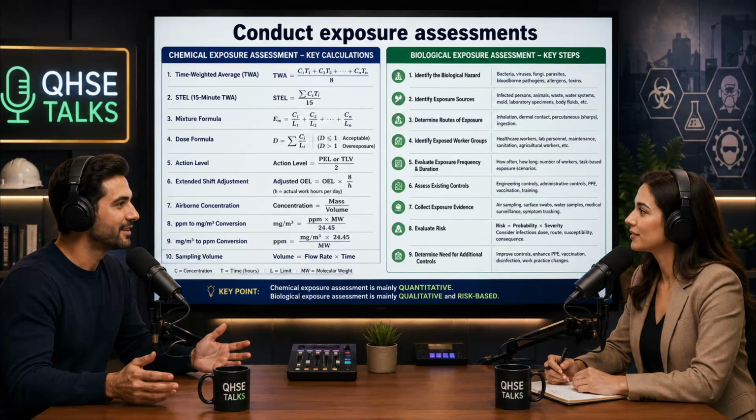Phew, now we evaluate the chronic full-day hazard. We run the TWA math. 15 minutes is 0.25 hours. So 25 ppm times 0.25 is 6.25. 10 ppm times 4.75 hours is 47.5. And 5 ppm times 3 hours is 15. The sum of all those is 68.75. Divided by the 8-hour shift, we get a TWA of 8.6 ppm. And with an allowable TLV of 50 ppm, their 8.6 ppm exposure is well controlled.